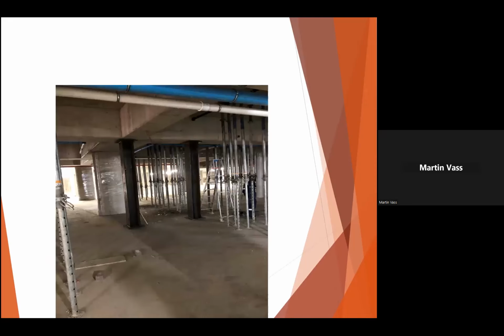So these are some of the new steel columns we're putting into the building. What will happen is these steel columns are put in, this is the upper basement parking. And same thing will be underneath these two additional columns underneath. And then those will go down to these new ground beams, which you saw just now. So that is how this building is going to be supported.